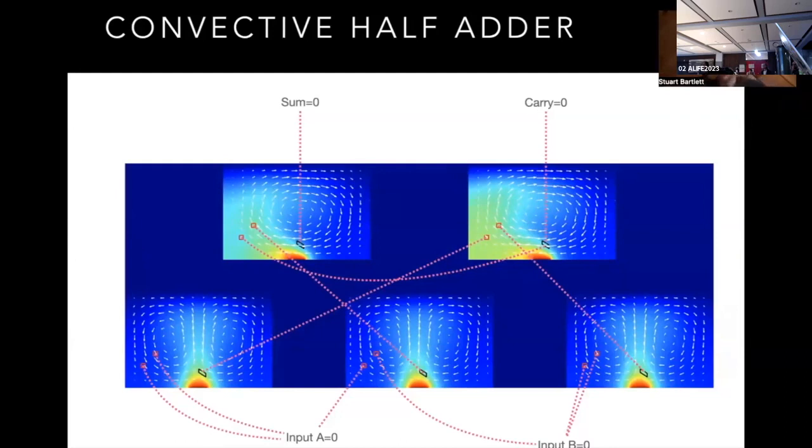So what we can see here is we've got the two inputs to our binary half adder. The first input goes to the two inputs of the gate on the left and the first input of the gate in the center. And the second input goes to the two inputs of the gate on the right and the second input of the gate in the center. And then we have the various links there constituting a binary half adder circuit comprised of NOR gates.